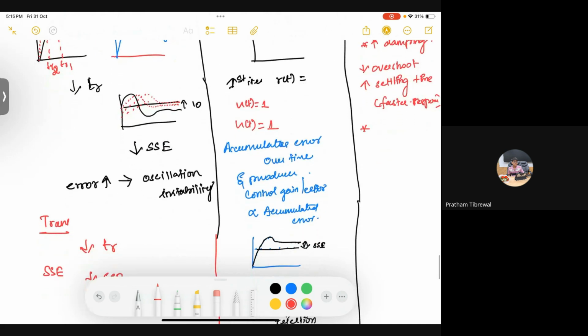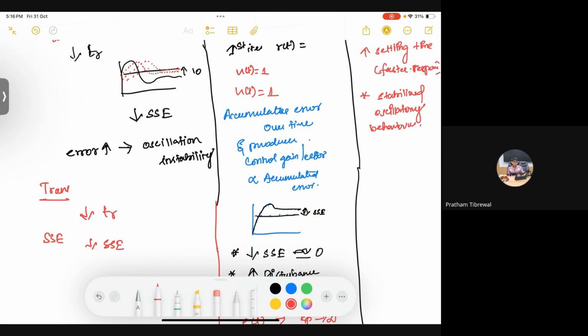And it stabilizes the oscillatory behavior exhibited by the system using the integral action. So when you use a PI controller and your error is not getting reduced, then we can consider going with PID, also increasing the D. With the PI, if you are getting a stable output, then that is enough, no need to go to D. And even if you get a stable response, but your settling time is very slow and you are expecting a faster response out of the system, then also you can go with a PID controller.